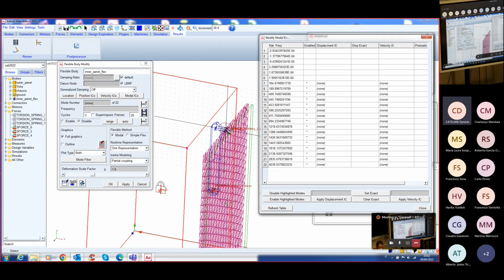If you have a spherical joint, all the modes participate, probably some of them with negligible contribution. If you have applied force, all the modes participate, probably with negligible contribution. If you don't have any connection, every mode participates, probably all of them with a negligible contribution. But you cannot remove these modes from your idea. Otherwise, you make a very big mistake.